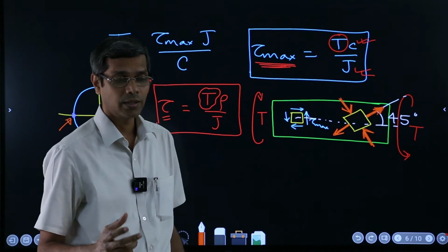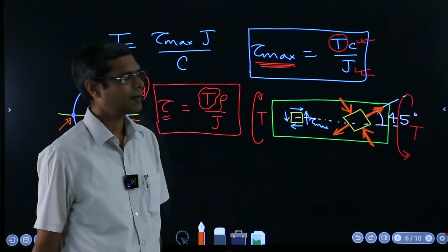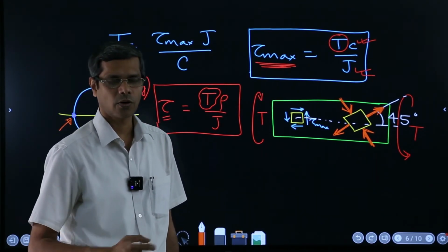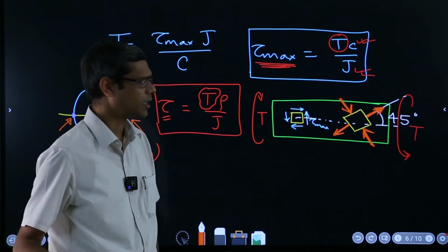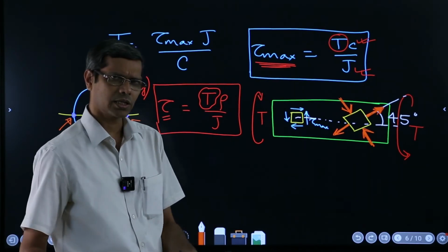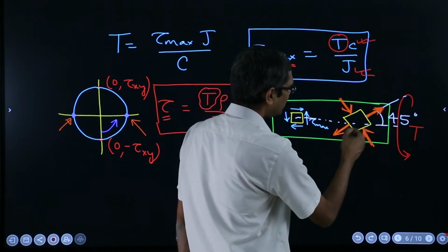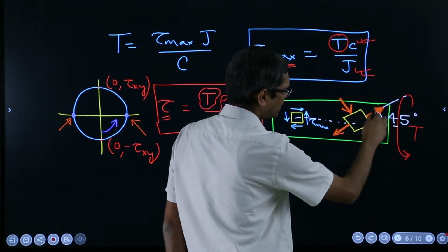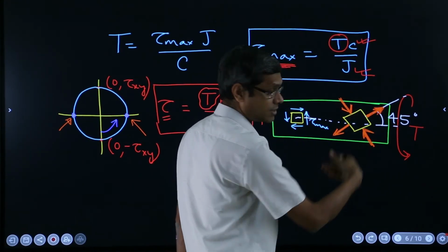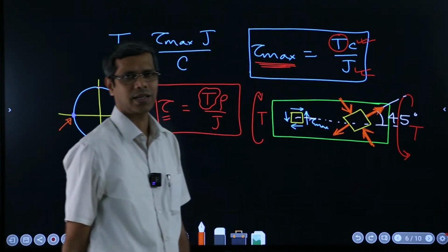In fact, the strength that they mention on the cement packets is the compressive strength of a concrete block under certain conditions. But the tensile strength is very low for any such brittle materials. Now, exactly the same thing happens here. So that means the chalk is very weak with respect to the pull that gets applied in this direction, but it is very strong to the push that gets applied in this direction.